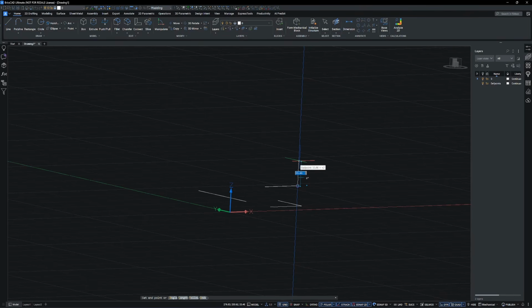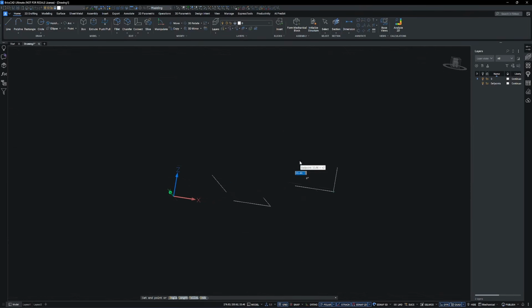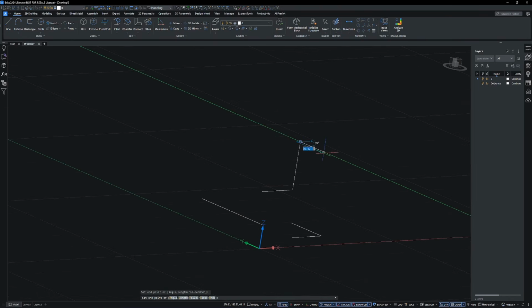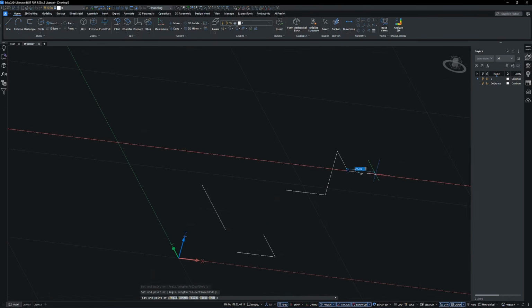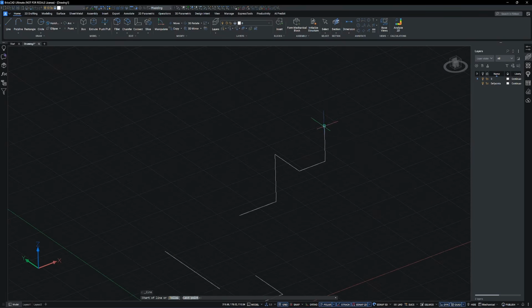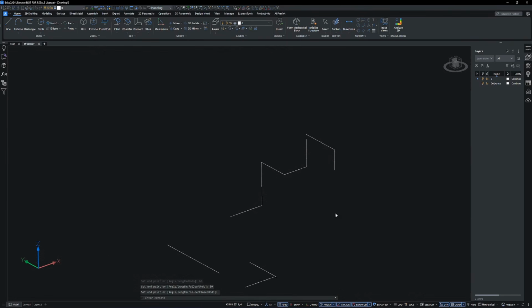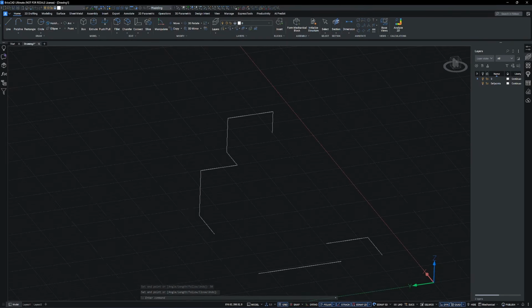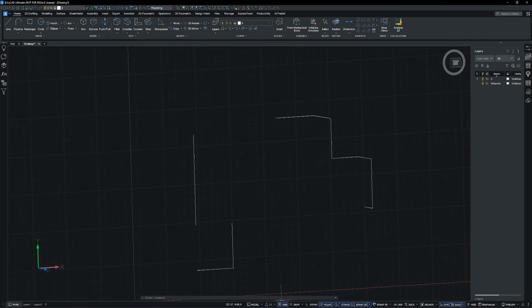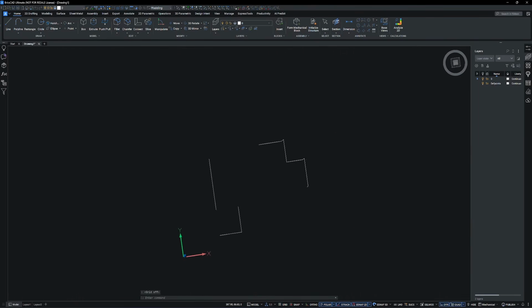It lets you create 3D lines orthogonally along the X, Y, and Z axes, shown with the red, green, and blue guidelines. When combined with the dynamic input function, you can type in the distance while drawing, which lets you create precise 3D lines. For the grid lines, I usually keep them turned off since they can be distracting during modeling.